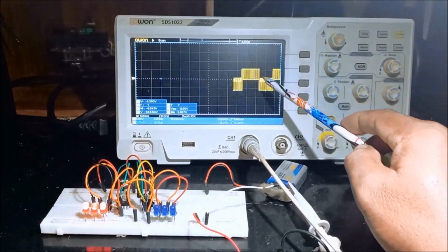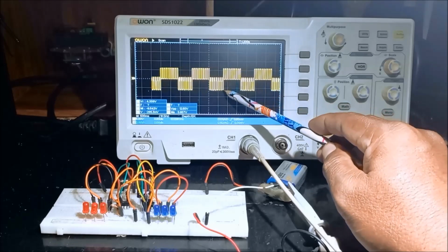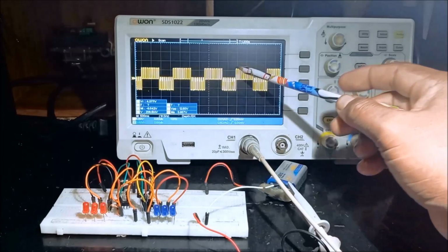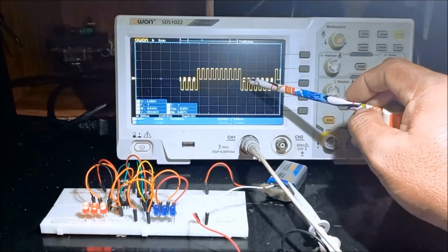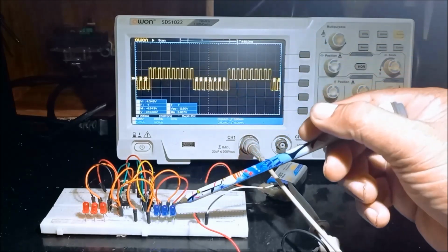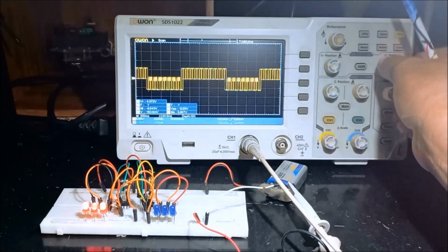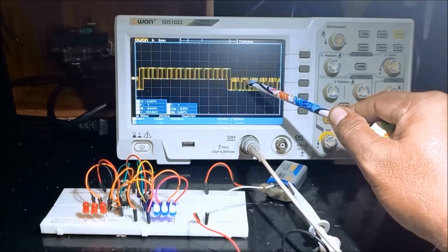So all in all, we have two sets of oscillator, belonging to the positive voltage and then the negative voltage. And the flickering of the LED is due to modulating the other side of the oscillator while the capacitor is discharging.